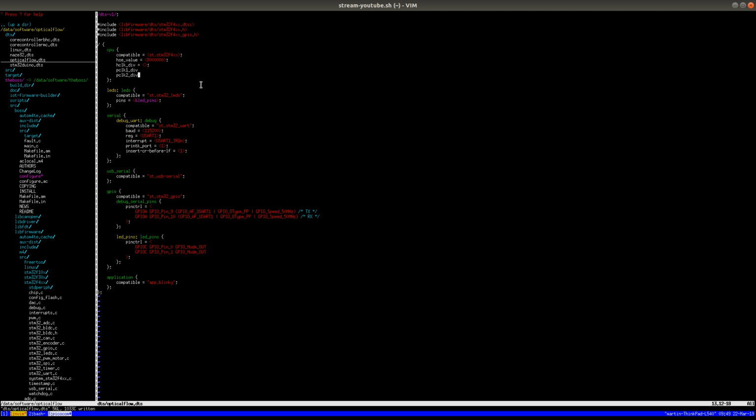So using the same code that I use, for example, for the F429 results in very weird behavior. You basically get a program that just crashes in very weird ways because it cannot load the correct values from the memory because it's running too fast. It took me a while to debug that until I finally figured out that my PLL wasn't really configuring things correctly.